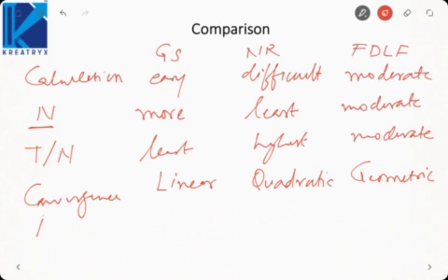And the last is accuracy. It has good accuracy. It has the best accuracy. And since it is based on assumptions, it has the least accuracy. It is the fastest but with the least accuracy. And remember, the Newton-Raphson method does not depend on the choice of slack bus, whereas the Gauss-Seidel method depends on the choice of slack bus. That is, in Gauss-Seidel you may or may not obtain the solution depending on where you have chosen the slack bus. And the biggest benefit with Newton-Raphson is that no matter what the size of the system, the number of iterations is almost the same.